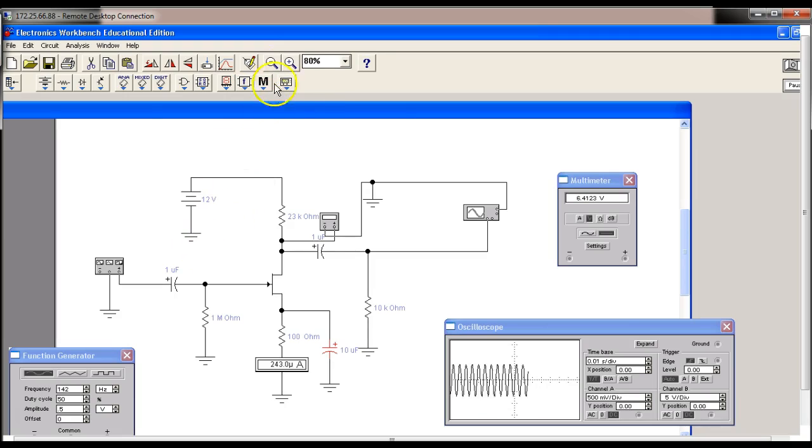You notice, let me get rid of a couple of these things. What's nice about the JFET is that we've talked about an important concept called impedance matching. The ideal amplifier, if we're going to amplify a signal, would have infinite input impedance and zero output impedance.